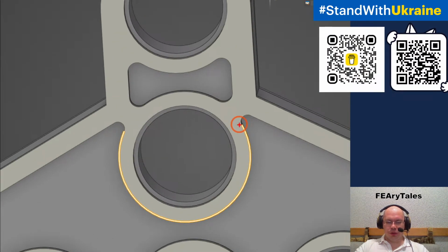Here is the same situation. If you leave the rounds and fillets here, you will have some problems. We will talk about it later, but let's talk about this type of behavior. And you can create something like that one here to produce the full hexa volumes.